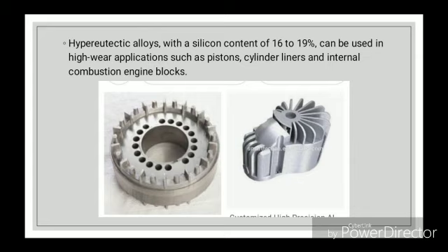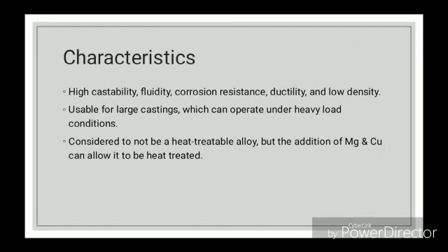Hypereutectic alloys with a silicon content of 16 to 19% can be used in high-wear applications such as pistons, cylinder liners, and internal combustion engine blocks. Characteristics: high castability, fluidity, corrosion resistance, ductility, and low density. Usable for large castings which can operate under heavy load conditions.